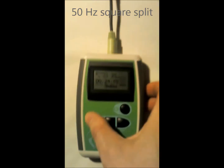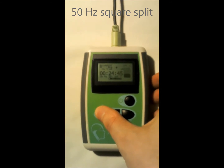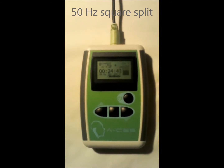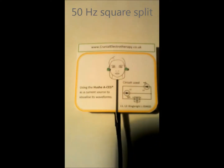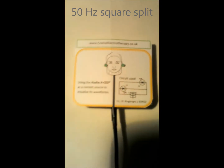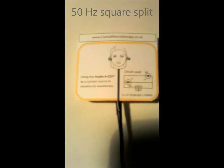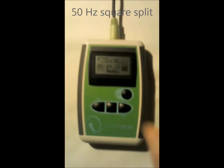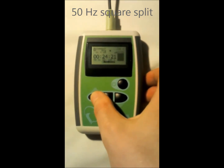At a higher level, if we go up to level 5 or so, I think we may have to turn off the light for a moment. You can just about see a uniform glow from each LED. This is a result of each LED rapidly being turned on and off about 50 times a second with a 50% duty cycle. If we go up to the maximum level, the effect should be most noticeable.